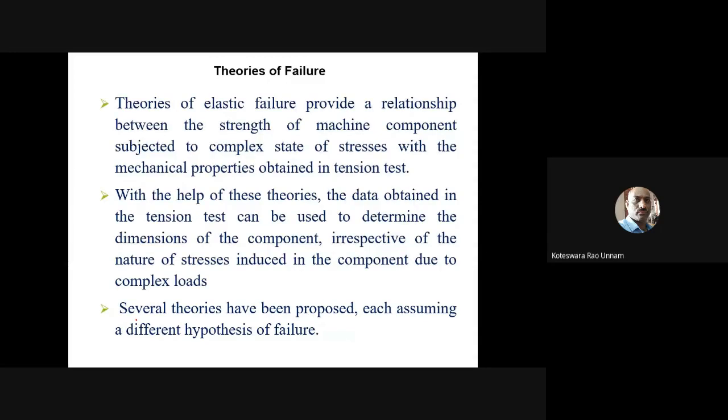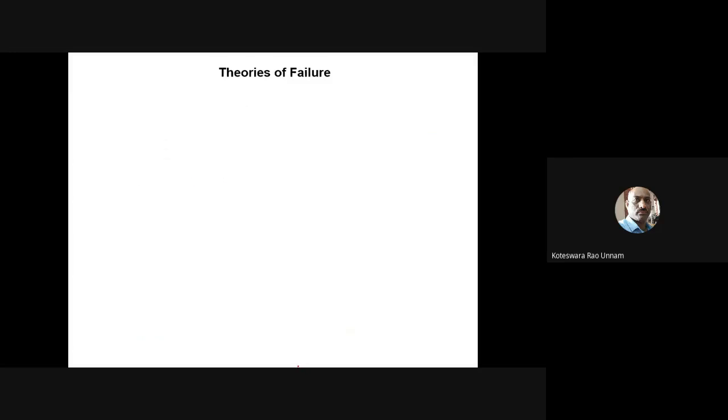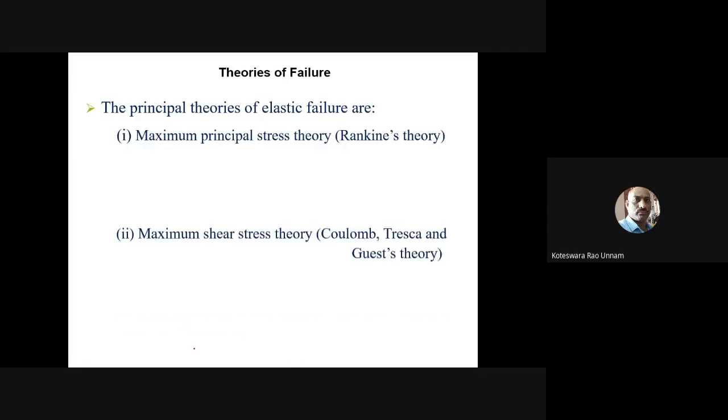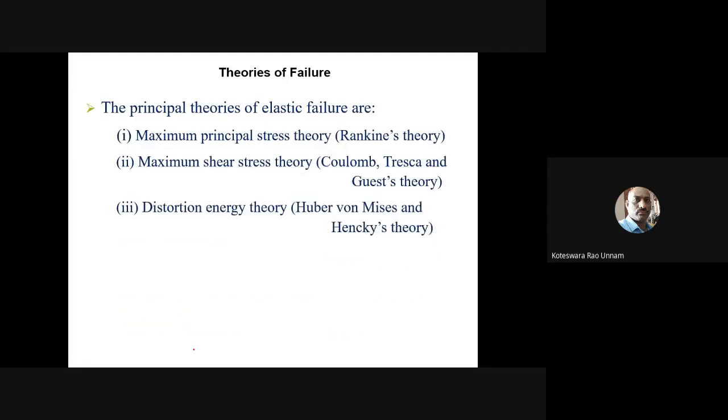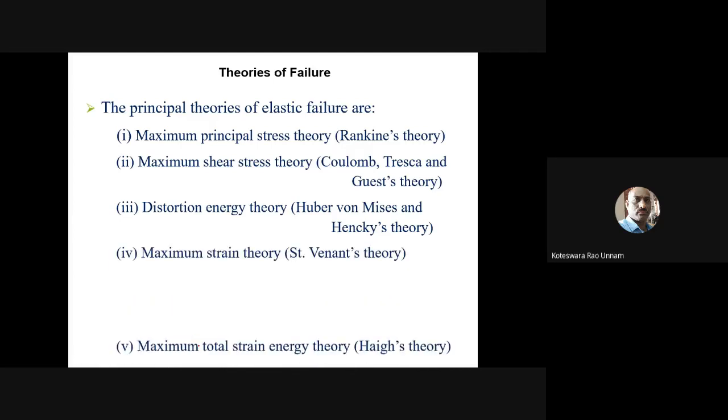Some theories assume that the component is going to fail because of the maximum shear stress in the component. Some may assume that the component may fail because of the maximum strain in the element. Similarly, maximum strain energy or maximum distortion energy in the element. Based on such hypotheses, several theories are proposed. Out of those, generally these five are the basic theories of elastic failure, which we use in designing machine components when they are subjected to